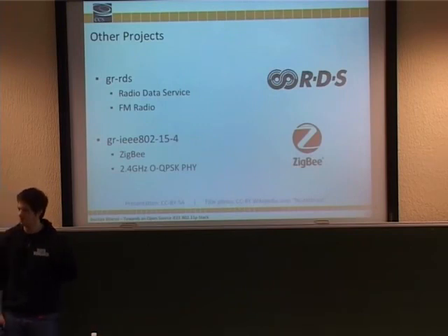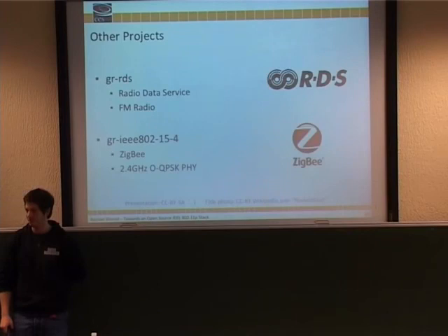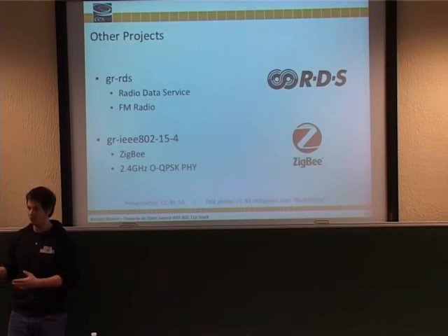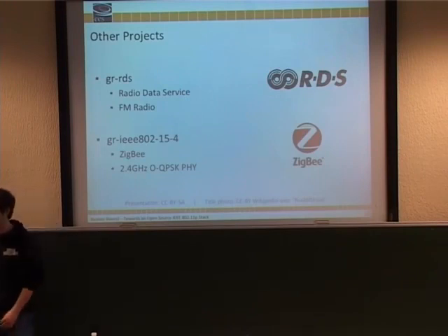Yes? Do you think with the next generation hardware you could meet the Wi-Fi specs with pure software radio? No, not with this approach, because I think if you really want to meet all these timing constraints, you have to move a lot of stuff to the FPGA, and then that basically means changing the whole architecture, even the operating system. No, even if you're using PCI Express, you can't meet the timing requirements.